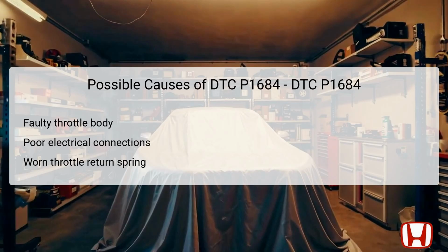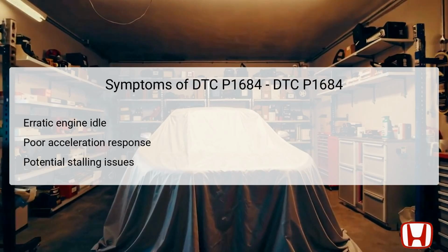Also, a worn throttle return spring may not provide adequate force to return the throttle valve to its closed position, causing the performance problem flagged by this DTC. Each of these causes can affect the vehicle's throttle response, and as such, must be thoroughly investigated during diagnostics to ensure reliable repairs.